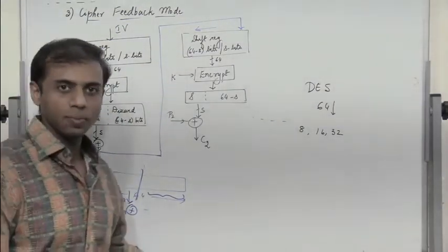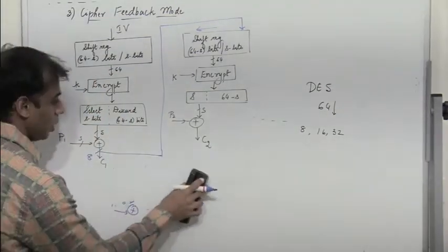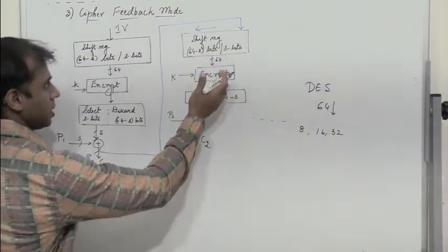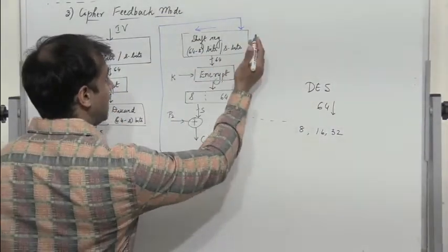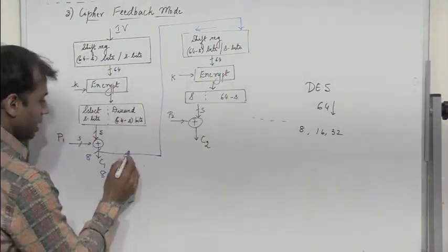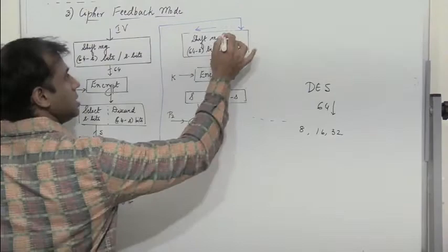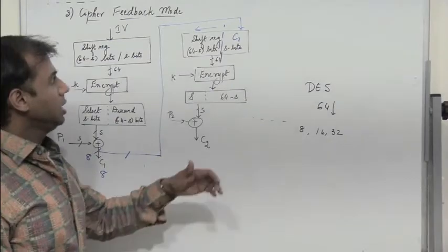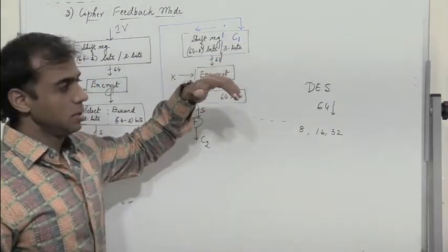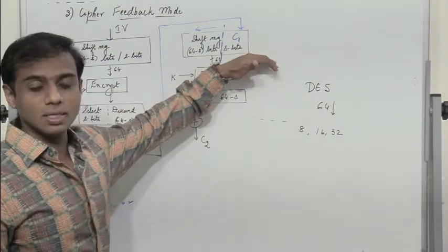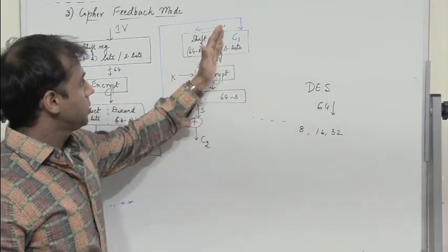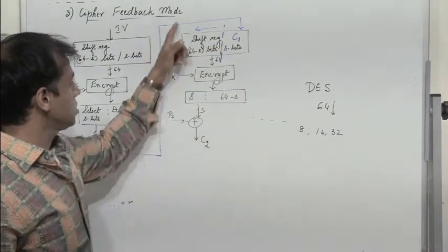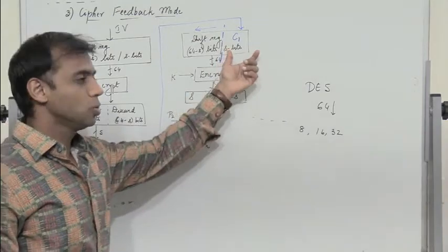So this is the first stage. Assuming S to be 8, C1 is of length 8. And what is done for the next stage, since this is a shift register, it is shifted left by S bits, and these 8 bits, that is C1, are placed here, in the LSB position of the shift register. So this is the most significant bit position, this is the least significant bit position. So we shift the register by S positions and C1 is stored here.